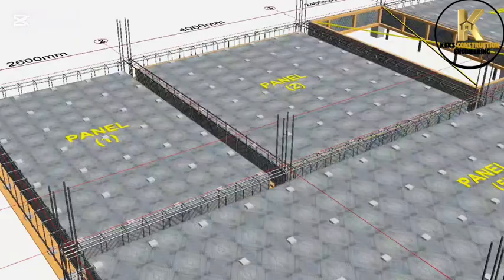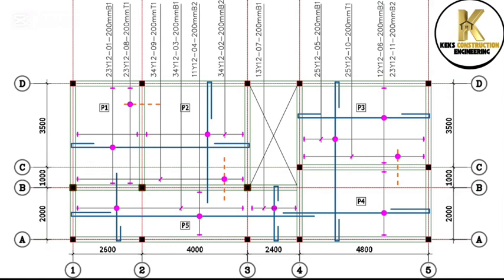Now, let's read our slab detailed drawing so we can interpret it and execute on site. Yes, this is the main work. Let's do it. The letter P, 1 to 5, represents slab panel 1 to 5. The magenta circle is used to indicate the rebars, while the ticks indicate the span where the rebar will be spaced. Now let's start with panel 1 and 2.